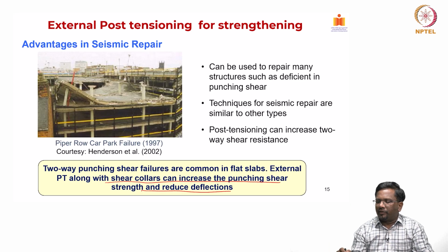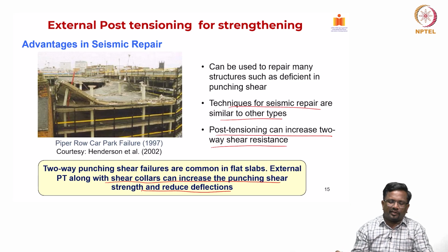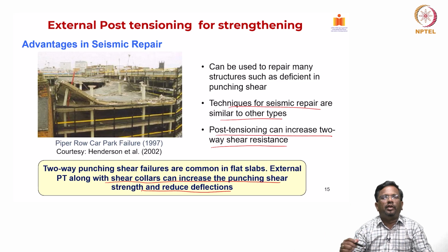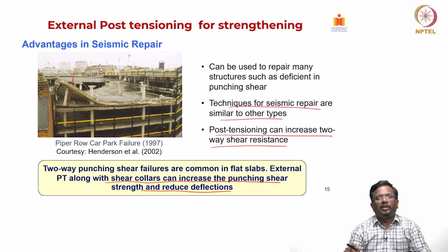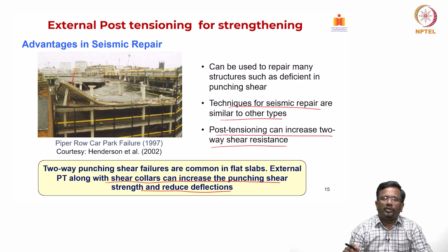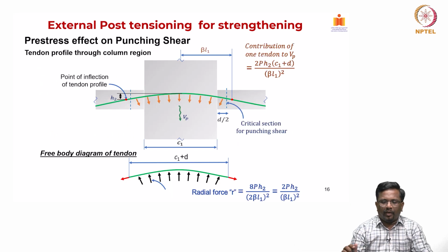So, the techniques for seismic repair are very similar to other types, and post tensioning can increase the two-way shear resistance significantly. So, I can run the cable in both directions externally and then along with some shear collars improve the performance significantly. And now, this also we have studied in the PT slab system.